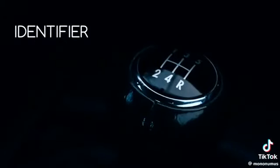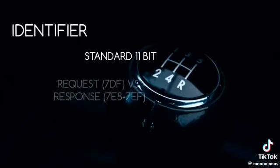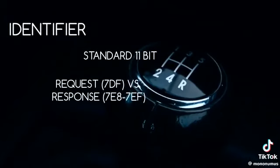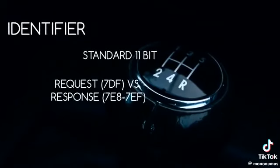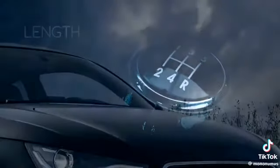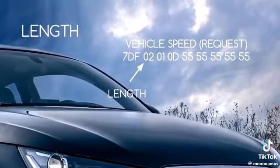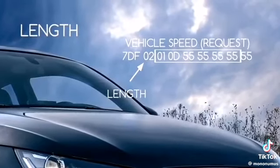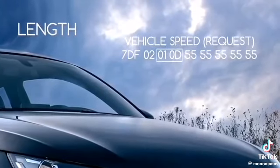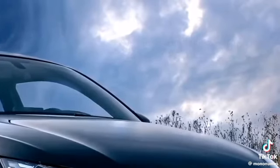Identifier. For OBD2 messages, the identifier is standard 11-bit and used to distinguish between request messages, ID 7DF, and response messages, ID 7E8 to 7EF. Note that 7E8 will typically be where the main engine ECU responds. Length. This simply reflects the number of bytes of the remaining data, 03 to 06. For the vehicle speed example, it is 02 for the request, since only 01 and 0D follow, while for the response, it is 03 as 41, 0D, and 32 follow.